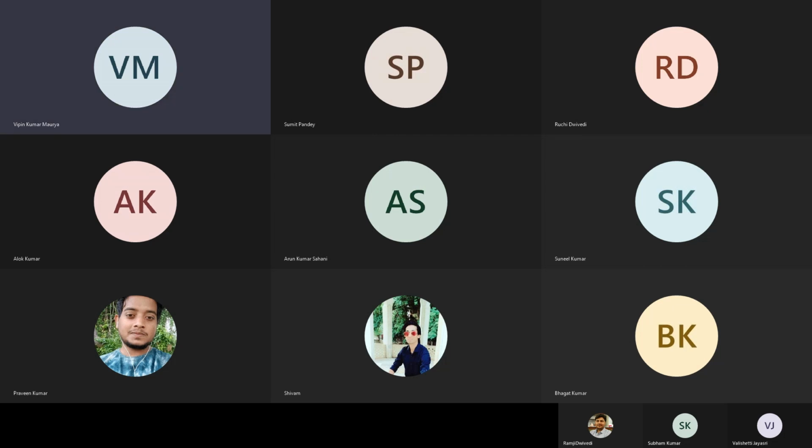To calculate your position, you need pseudo ranges, or ranges, from the satellites. In GPS we are using satellites, so you require a minimum of 4 satellites to get the observations. Based on those observations, which are pseudo ranges, you calculate your position. There are many errors along the way from the satellite end, in the atmosphere, and also at the receiver end.